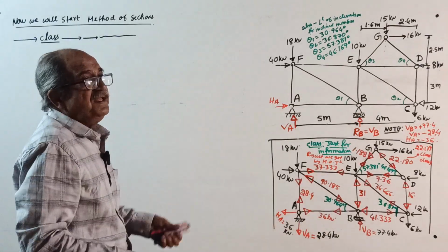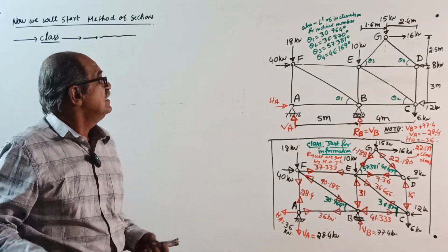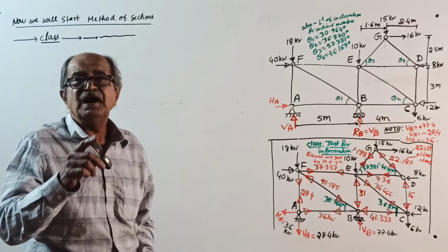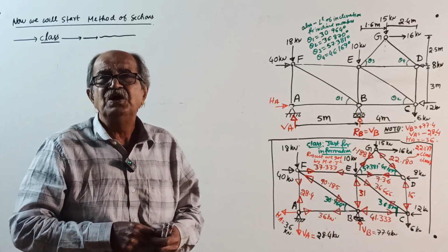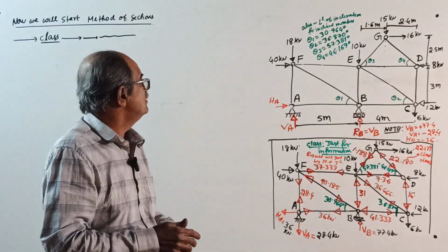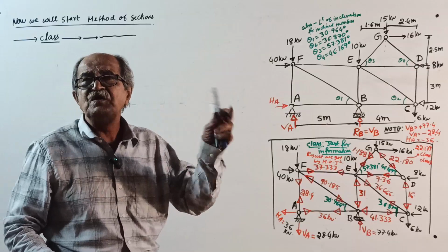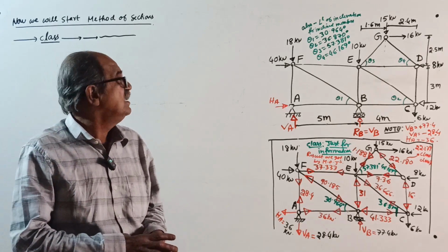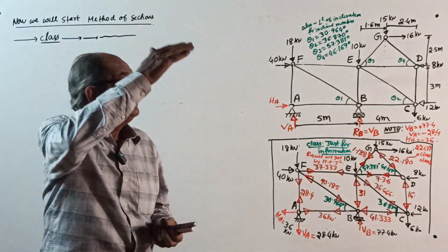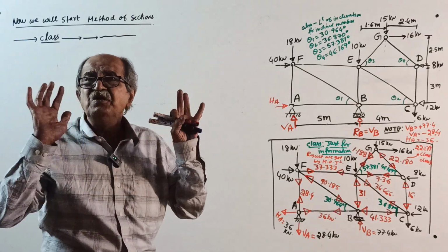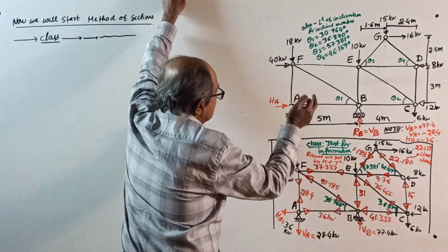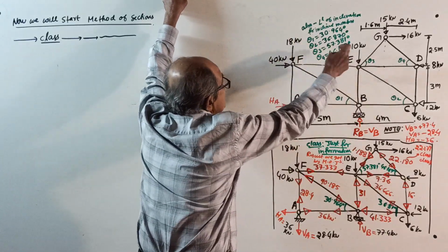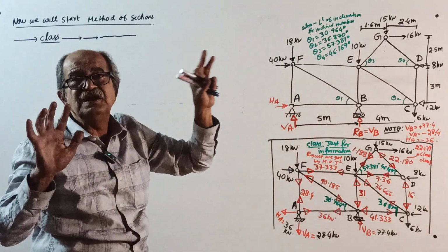Then, if it is an independent question, once you cut or pass a section, you consider equilibrium of any one side, whichever side is easier for you. In case you are solving a both-end-pinned truss, consider the free end side, because you are not finding the reactions. When you consider equilibrium, on that side write all external forces, like support reactions and other outside external forces.